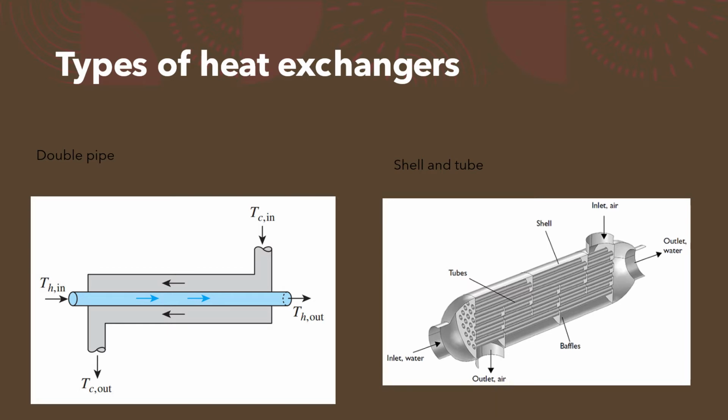The next configuration is the counterflow. The main advantage is better heat transfer compared to the parallel configuration. In the counter configuration, the liquids enter from opposite sides and flow head-on and exit at opposite sides. The double pipe heat exchanger is used in boilers and compressors.